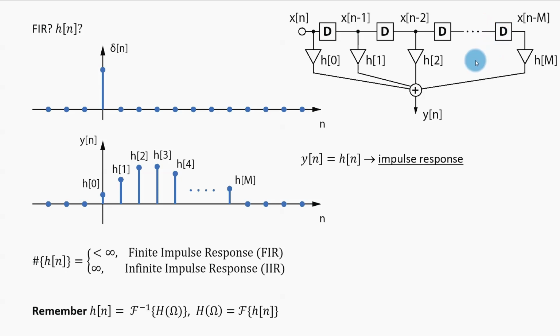The time delay is very often half of the order of the filter, but in contrast to the filtering in the spectral domain, you do not have to wait for your signal to be recorded and filter it after. The signal is being filtered as the data is coming in. Also, you do not need to store the entire signal. As those numbers are coming in, they are passing through these delay elements, through these memories, and once a number gets here, it falls out of the filter, it's forgotten, and you do not have to store it anymore.